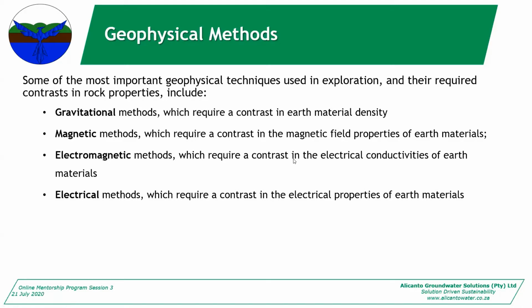Now with this, the key thing with geophysics is that it shows you a contrast. That is all that geophysics shows you. It will show you that one thing is more than the other. It's more dense, it's more conductive, it's more resistive. So without understanding the geology of your area or the expected characteristics of your area, the geophysics doesn't really show you a precise answer unless you know what to look for.